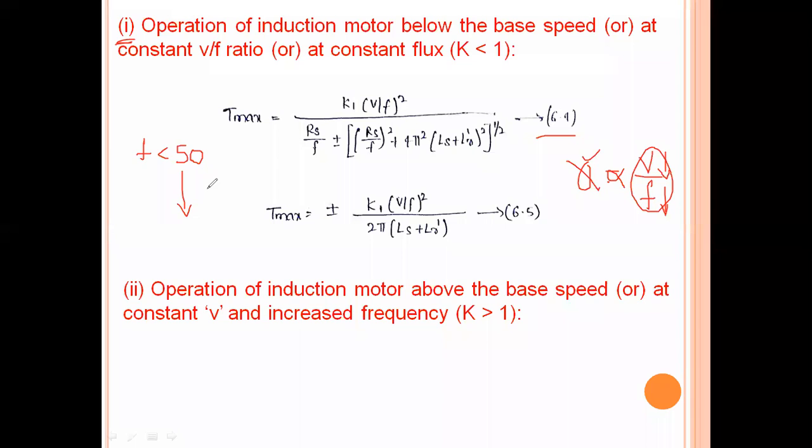Otherwise, if the flux is saturated, if the flux is more for the lower frequency, then the motor performance will be degraded. So in order to avoid that condition, we need to vary the supply frequency also. It is mandatory to vary the supply frequency so that the flux will be maintained constant and will not be saturated. The induction motors are designed to operate at the knee point of the magnetization characteristic to make full use of the magnetic material, which means the flux.